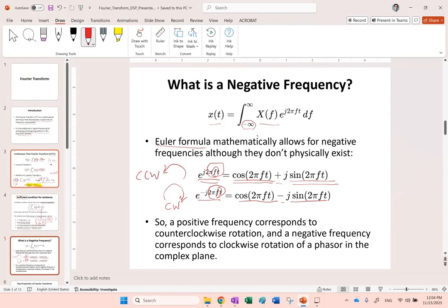You know that when we measure the angle in the xy plane about the z-axis, we consider counterclockwise positive and clockwise negative. So when we say negative frequency, we are not really talking about negative physical frequency. We are just talking about a clockwise rotation of the phasor in the complex plane, and positive means counterclockwise rotation of it. So here we account for both directions of rotation. The actual physical frequency is the absolute value of that number. It's just the direction that makes it negative or positive. So I just wanted to clarify this.